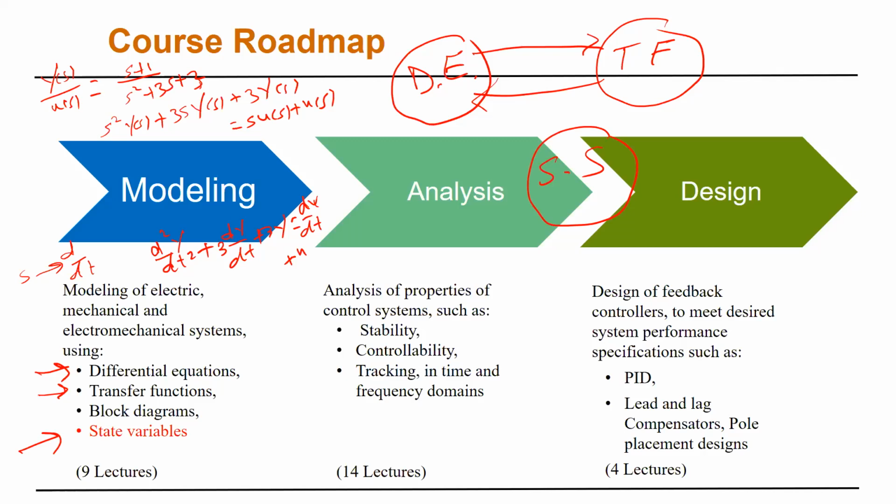Simply, rather than working with an nth order differential equation, I will work with n first order differential equations. That is basically x dot equal Ax plus Bu, y equal to Cx plus Du.